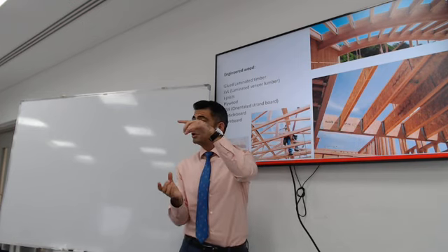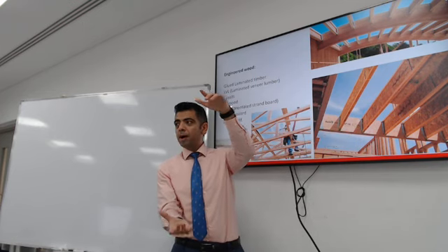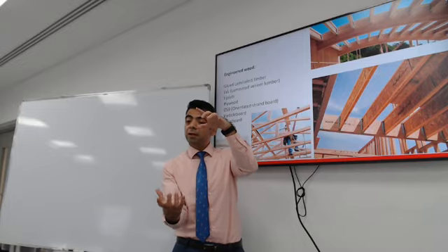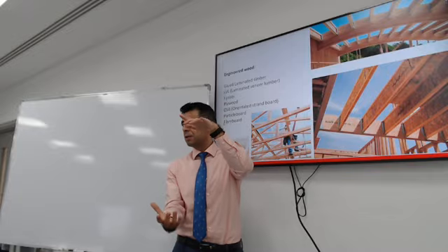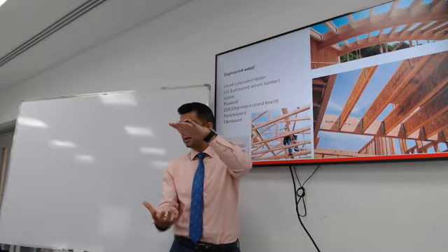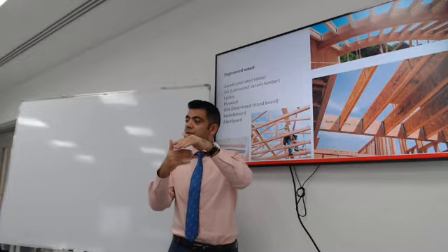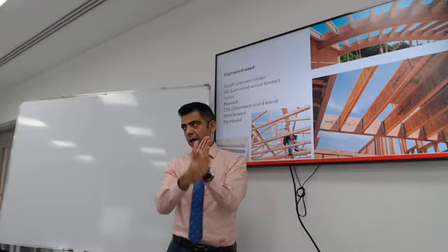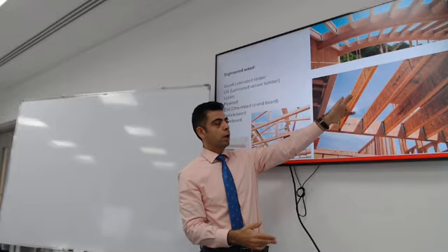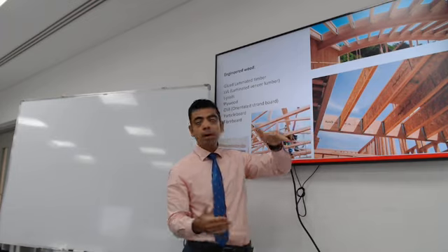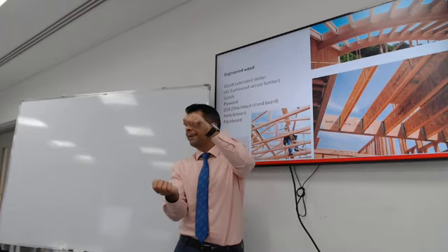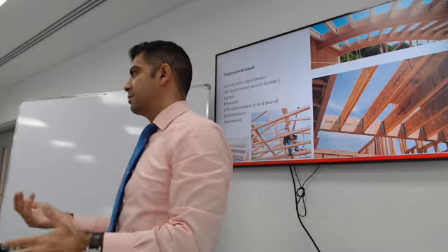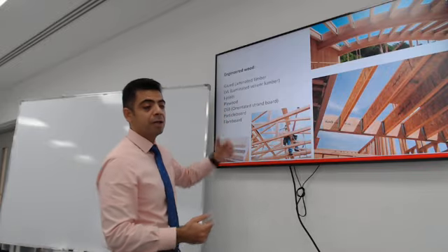I want to point you to this product over here. This is called an I-joist. The top and bottom flanges are big. It's like an I-beam. This section is very effective because it has material at the top and the bottom of the section. This is where most of the tension and compression and bending is. And the web is just to resist the shear. So it's made out of an engineered wood, maybe an LVL, or some sort of engineered wood for the web. And the top and bottom could be from a different wood material, and then you glue them together or connect them together to create joists. So that would be an example for engineered wood.